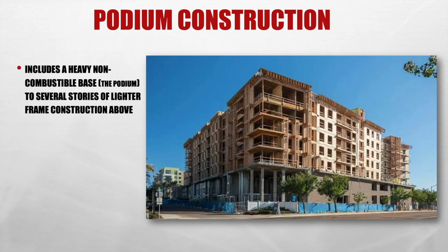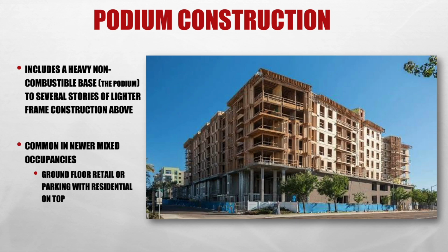One example that I can think of for hybrid building construction is podium construction, and again, this is becoming more common. Podium construction includes a heavy non-combustible base, which is the podium, and several stories of lighter frame construction above, so more wood frame construction. This is common in newer mixed occupancies where the ground floor might be used for retail or for parking with residential on top.